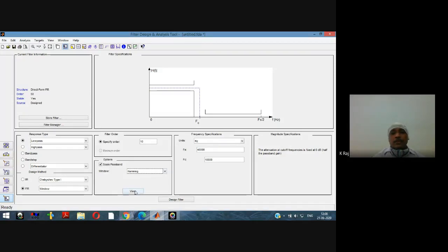As we know, if we are going to design the FIR filter, then that filter will be described by this frequency specification. But what is the drawback here? When this is transformed from the frequency domain into the time domain, what will happen? There will be an infinite range of time. That is, it will exist for an infinite range of the sequences, and that is not physically realizable.